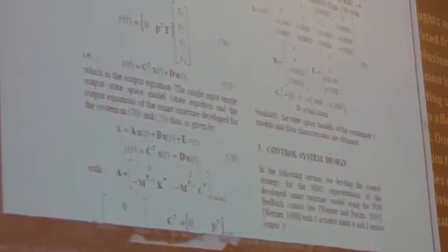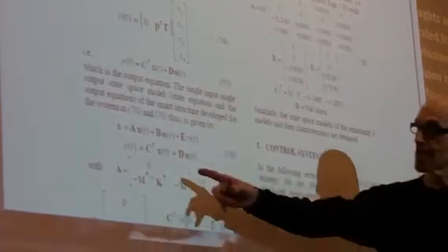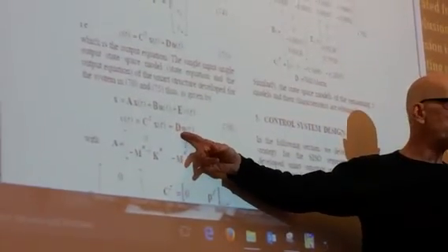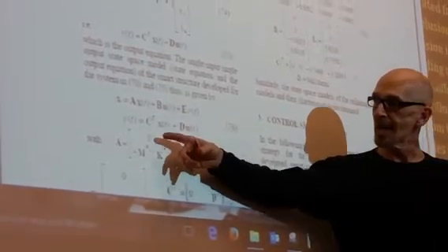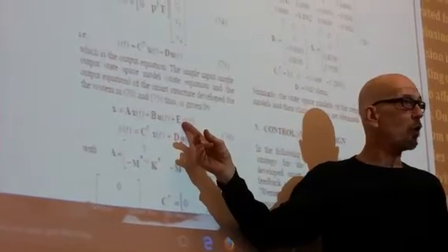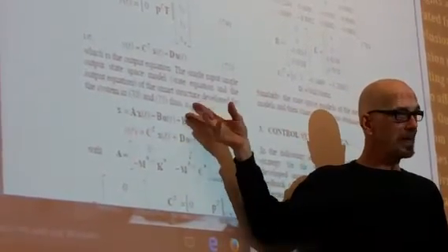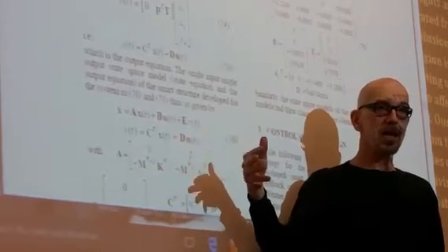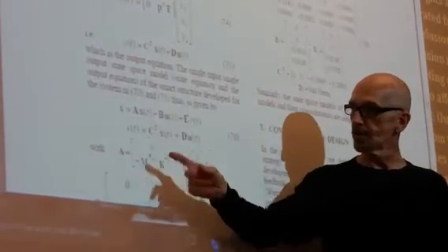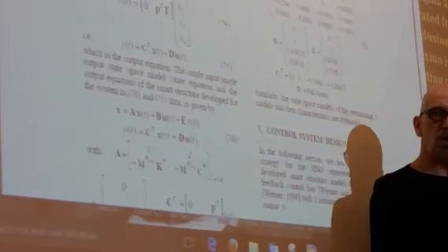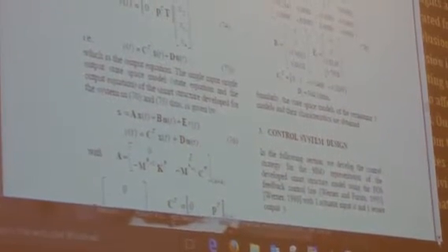Then they do the control system design, so they end up having a matrix. Look familiar? We did this in the beginning of the course, and you did this in 355. X dot is AX plus BU. This is the control law now. And then your Y is your output. So here's state space. You can say, yeah, I know how to get a transfer function from this, right? You Laplace transform, take the inverse of SI minus A, and then you get your transfer function matrix.